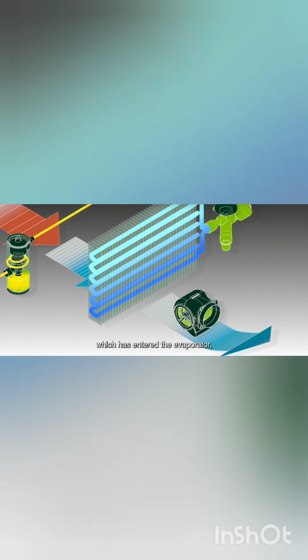The refrigerant, which has entered the evaporator, evaporates by absorbing heat from the air entering the occupant cell. The temperature rises to approximately 5 degrees C at the evaporator outlet. On leaving the evaporator, the desired outcome is that all the refrigerant is fully evaporated and returned to a gaseous state. On systems with a flow restrictor type expansion valve, this isn't always the case. On these systems, the refrigerant will pass through a catch tank before making its way back to the compressor to start the cycle again.